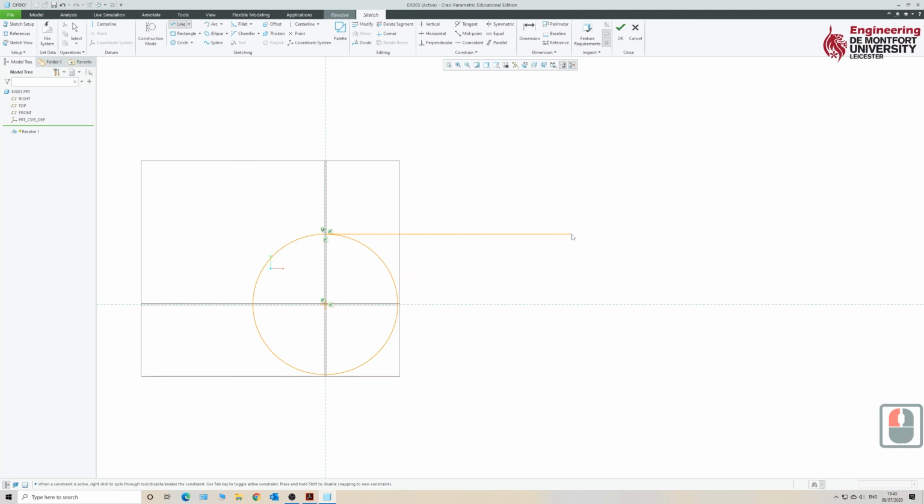I'm going to click. I'm going to take the cursor down, click, drag it across to the right, again horizontally, click, and then move the cursor vertically down until you're touching the center reference line. And then we just click here. We press the middle mouse button, and then we press the middle mouse button again.